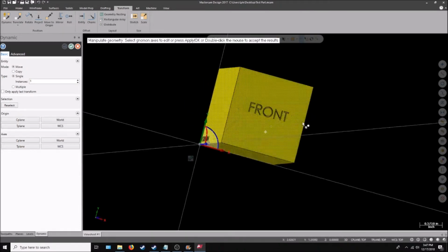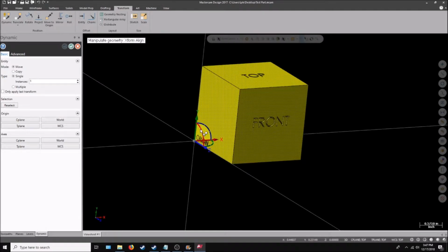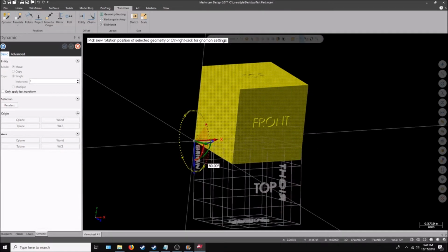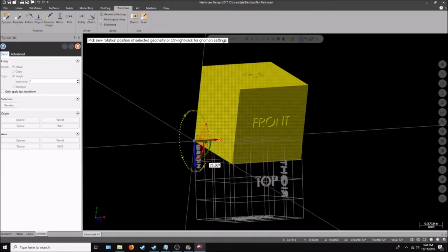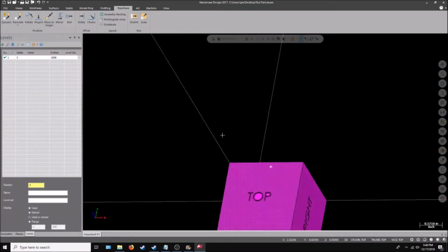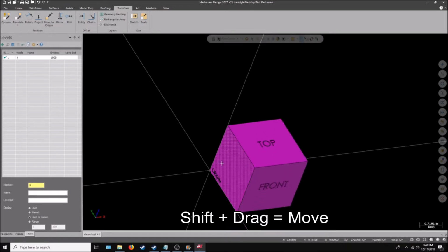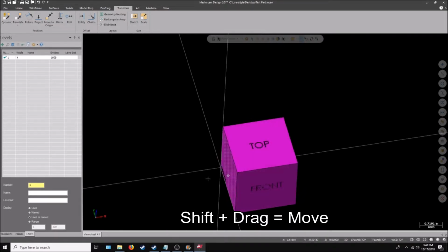The top view shows us this front view, right? So if we want the top view to really be the top view, I'm going to do that. All right. And now we've got to make sure it's Move, or it will just create another one, and then we'll have some monstrosity. So we're going to say, yeah, we wanted to move it there. Cool. So now it's where the origin actually should be, which is the bottom left of this part.